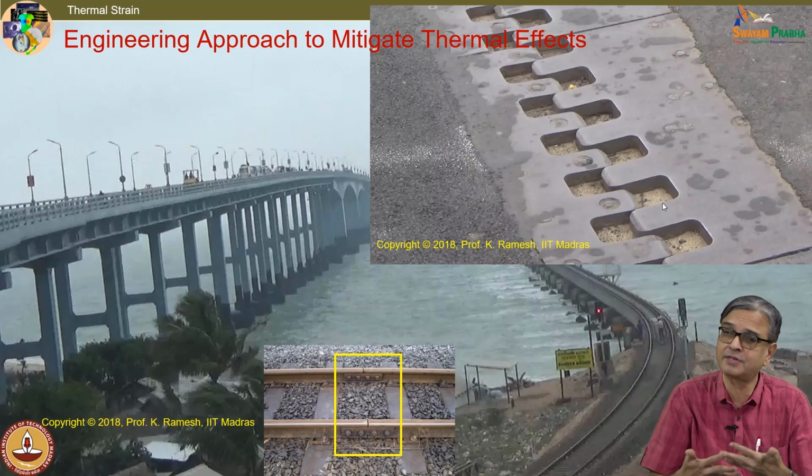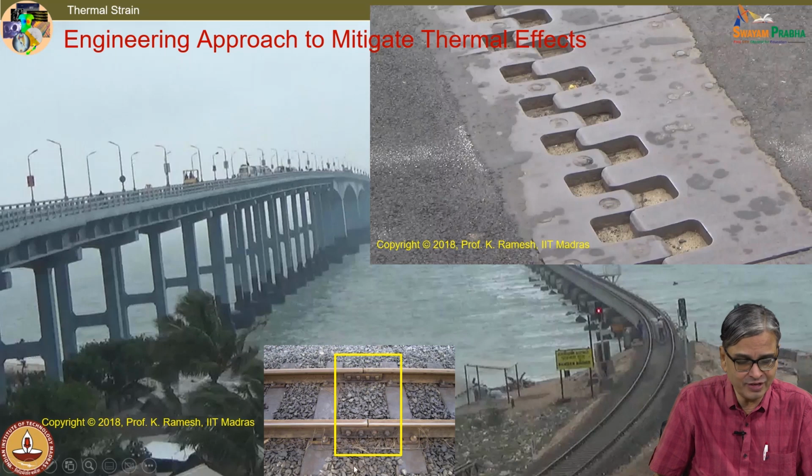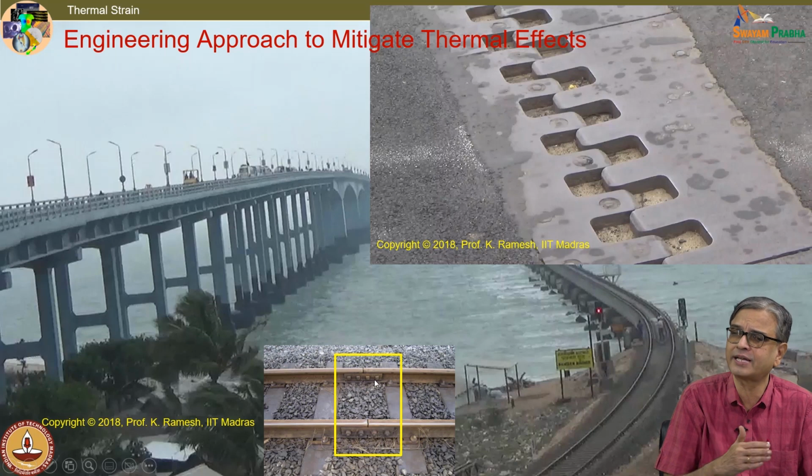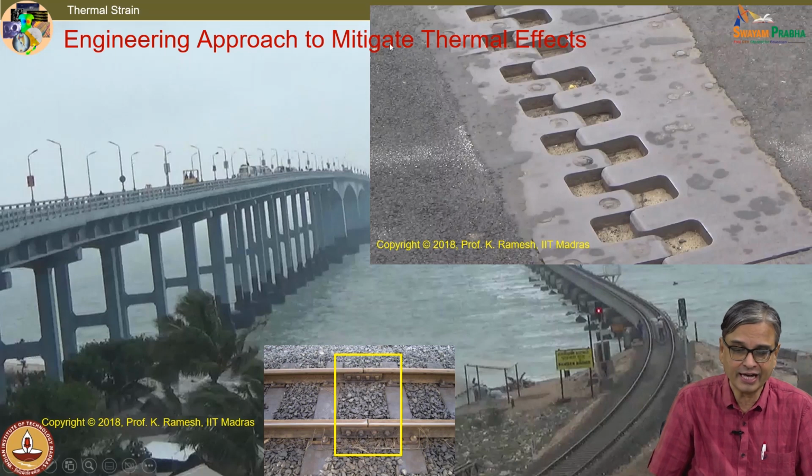And when you go to the rails, conventionally what they were doing is you have a rail of particular length and then you have a gap in between them and then you have a bolted connection. This was the old type of handling the thermal stresses in the case of railroad. So, this is on an actual concrete bridge like this.